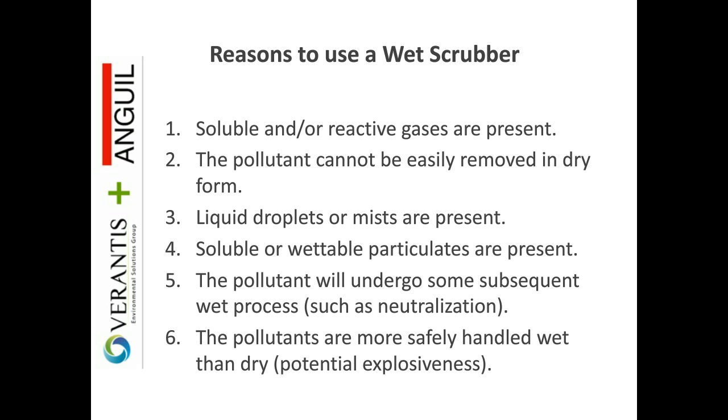We look at the rationale of why use a wet scrubber instead of some other type of technology or a dry scrubbing technology as an alternative. A wet scrubber is going to typically be an excellent fit for inorganic acids, which is why we're talking about wet scrubbers here today with respect to thermal oxidation and its off gas. But just in general, if you're dealing with soluble gases, gases that are reactive with water or with an aqueous solution, a wet scrubber is generally going to be very effective.